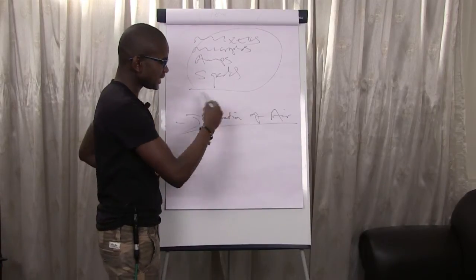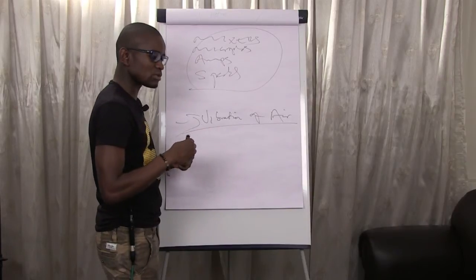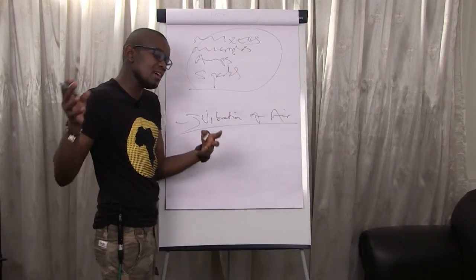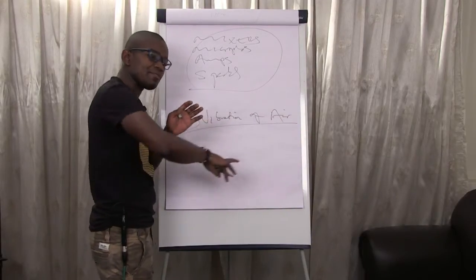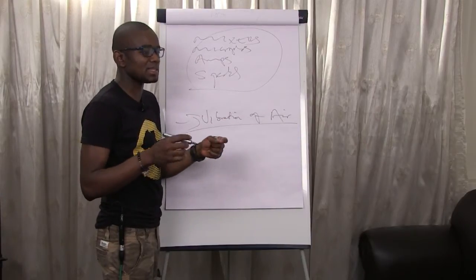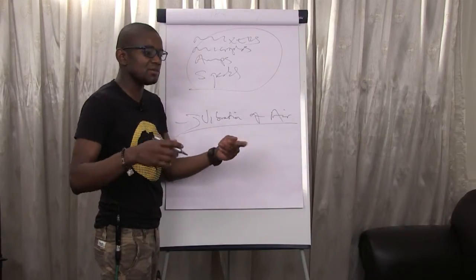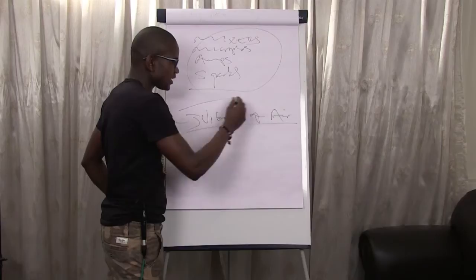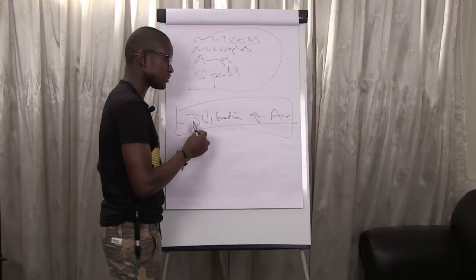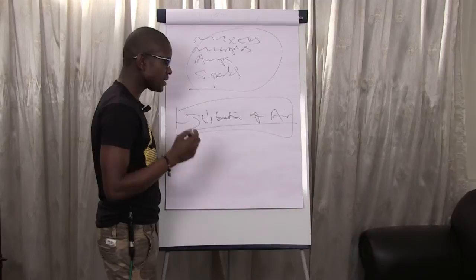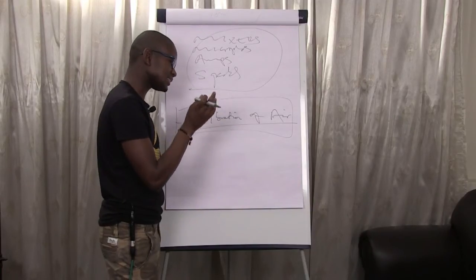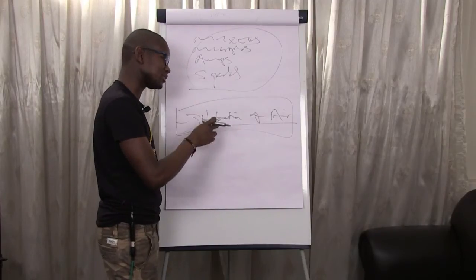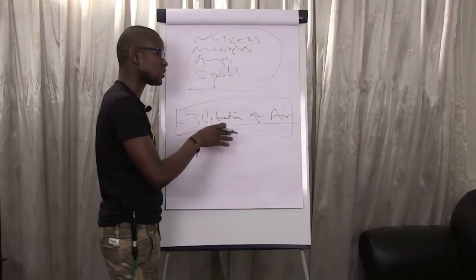And just understanding this part also means that if you have a smaller sound system and you've got lots of people, you have to drive the small sound system hard enough to cover the entire audience. But if you've got multiple sources, you have to drive the system less and still cover the people. So all of that comes from the concept that sound is the vibration of air. For me, this is the heart of it all. Understanding this basic principle, understanding this particular definition, giving respect to it and applying it every day as you do sound engineering really helps.